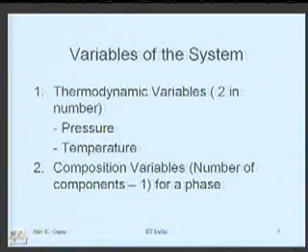But if I have three things, like in steel, I have iron, I have carbon, let's say I have manganese. Steels can have more than three. I'll just take an example of three: iron, carbon and manganese. I say it contains 0.2% carbon and it contains 1.8% manganese. Right? Then the amount of iron is defined, 98%. So I have to define one component less in number of variables. That's what I have. Number of components that are there in the system minus 1.